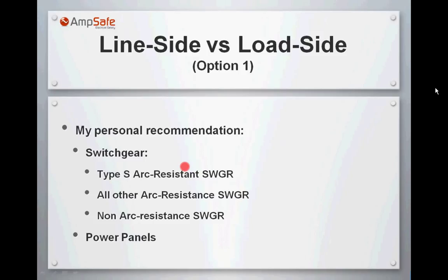But make sure that you have a lot of training and understanding. Everybody has to understand that they have to check every panel when they're going to work to see if there is a main overcurrent protection device. If there is a main overcurrent protection device, they're going to see two labels on the panel. And they have to understand what those labels mean, which section applies to one label, which section applies to the other, okay?